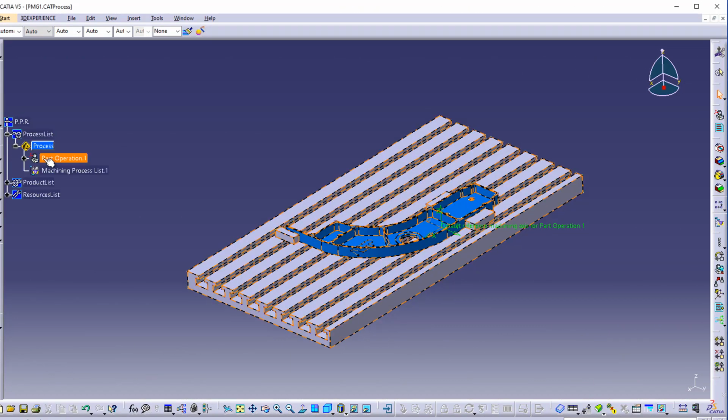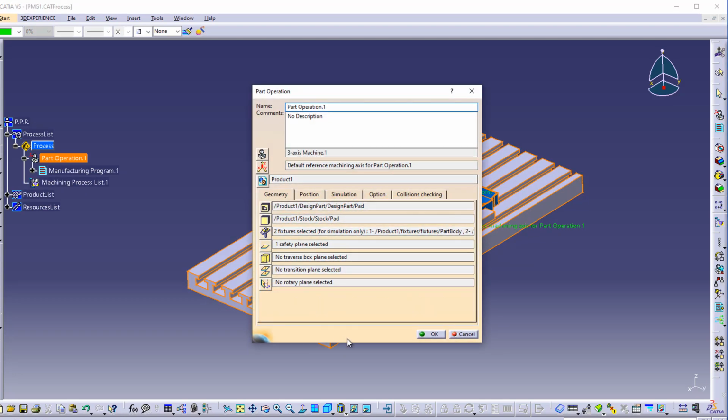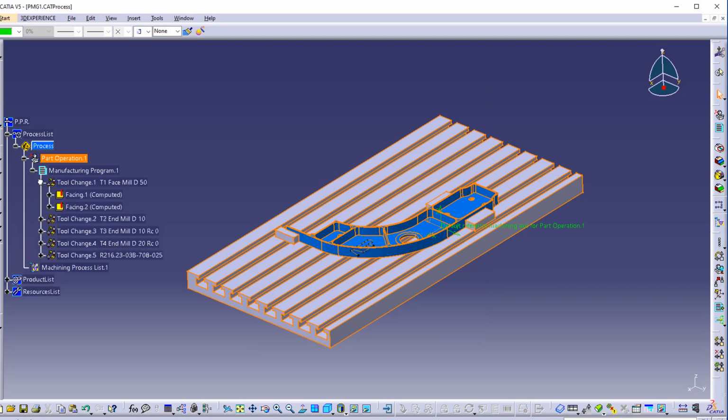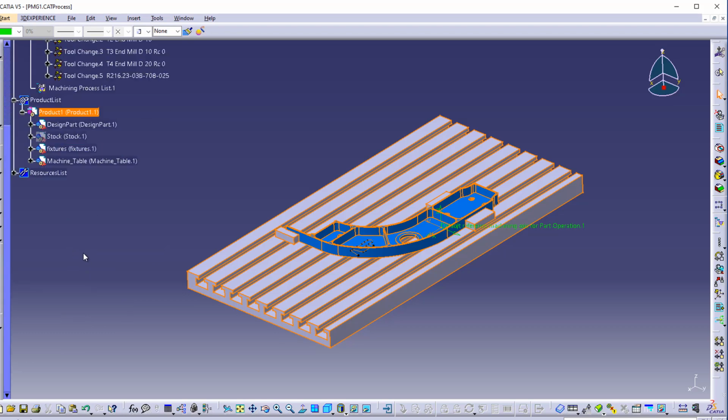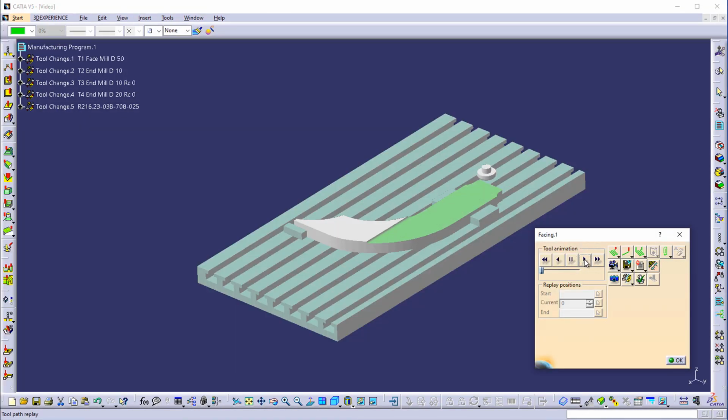Having created the final part using Catia's standard part design functions, the NC machining process begins with the creation of the starting volume. This is a model of material from which the part will be cut and can be left to Catia to be automatically defined or defined by the user in cases where the part will be cut from an offcut from a previous project. Next is the selection of the machine and axis system, along with tool catalogs, speeds, and feed rates.